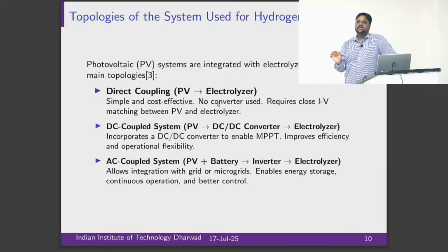That voltage I want to control, and through that control I want to switch some DC-DC boost converter. That's what you can do. Any time voltage tries to go down, you try to make it up. For that, current will be automatically adjusted, so that you maintain your MPPT point.